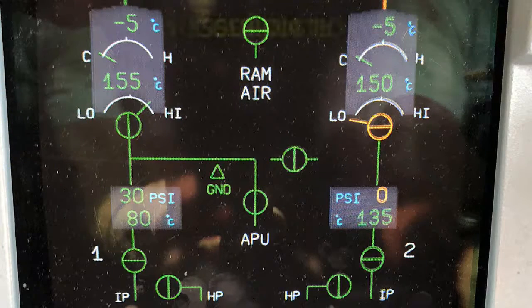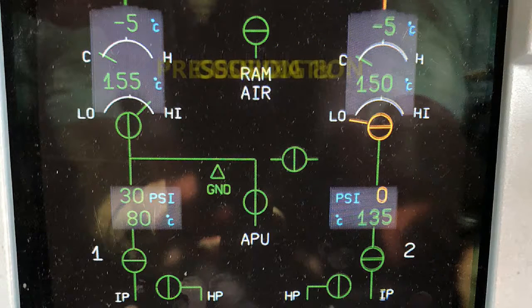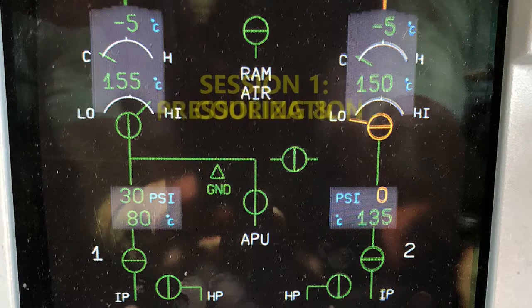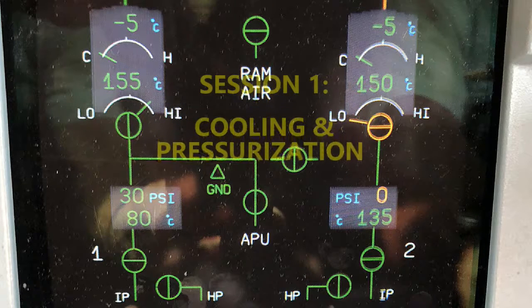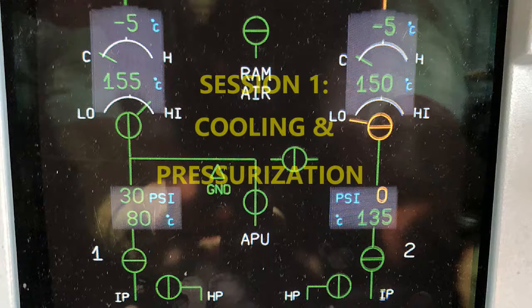So when it's on, and we're assuming there's enough bleed air to run this so that the valve can actually open, then that's what's going to happen when you push the push button switch to on. It's going to open up that valve. Now, the only time it's going to actually shut it off automatically is if the fire button's pushed, or there's an engine start that's initiated for 30 seconds, then the valve's not going to open yet. If there's an overheat detection, then the valve's not going to open, or the ditching push button's on. So those are conditions where the valve will not open. But otherwise, it's going to open when that push button switch is in the on position.